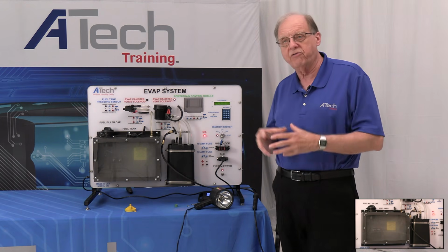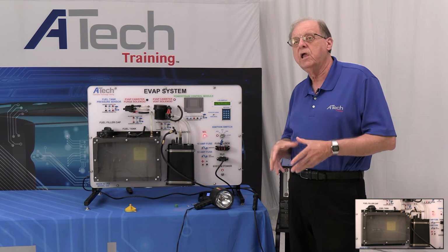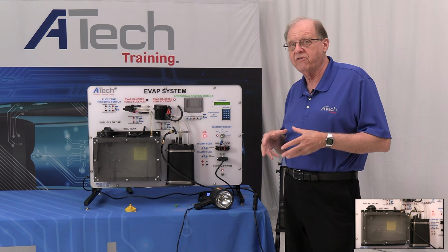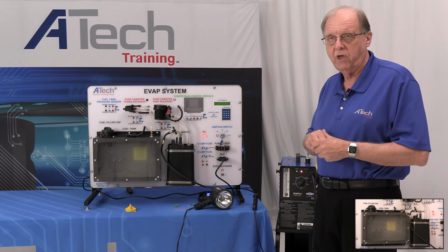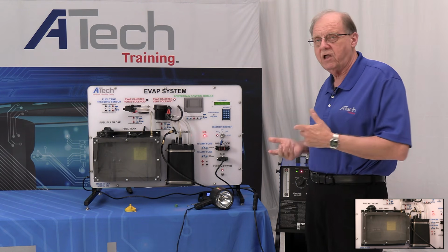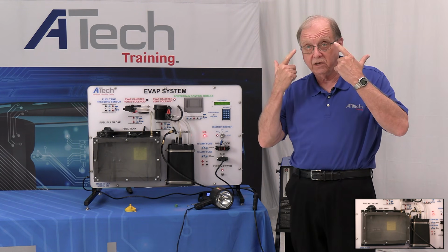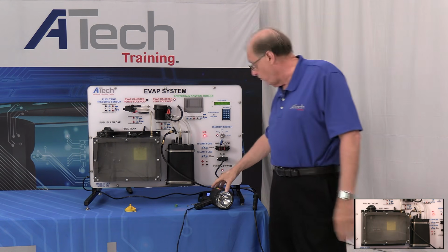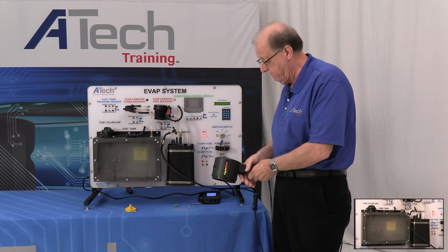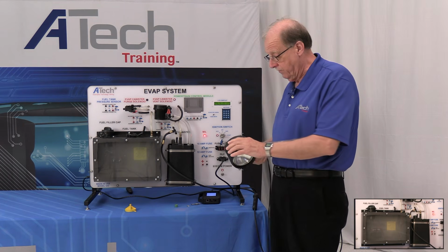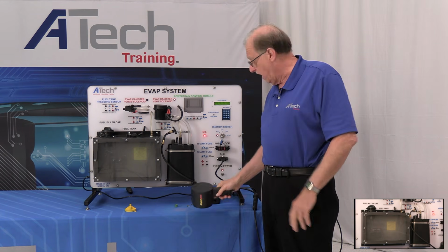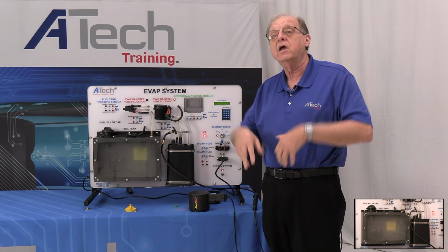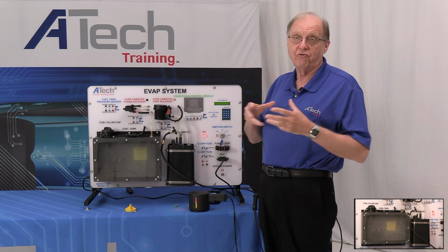Now the other thing is there are some smoke machines on the market that have a dye in it, all right? The process of using the dye is to leave a residue as it leaks. So you would have an ultraviolet light and a pair of glasses that you're going to need, and you just go down with that light. My personal smoke machine, which I haven't used in quite a while, has one of these. It also has another light that puts out UV light so I can test the system. So there are different ways of doing it.